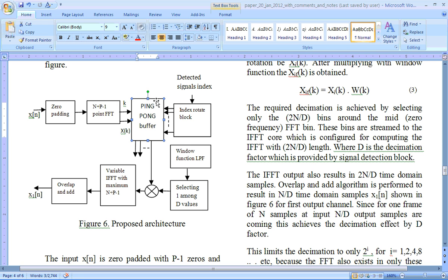Or one possibility, since there are only 2 read ports for one block RAM instance in FPGA: let's say you want to support a maximum of 6 signals for simultaneous down sampling rate conversion. Then you put 3 block RAMs. That is not an efficient scheme, but in FPGA it is a limitation we have to live with. But it is still acceptable, because block RAMs are not a costly affair in FPGAs. Even a low cost FPGA comes with 1 megabit of block RAM. A normal Spartan 3 also has a megabit of block RAM.